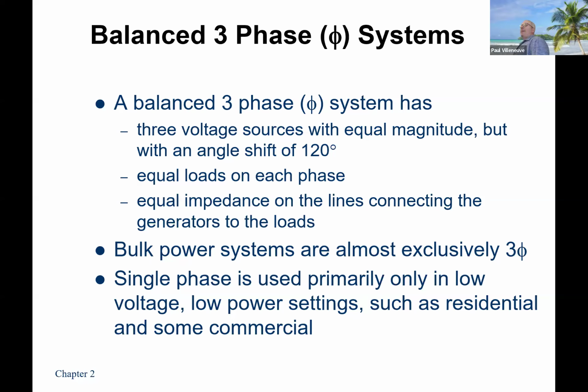We'll talk about three-phase power systems because that is what the utility world works at. This building is fed with a three-phase transformer. I should back that up. It's 3 single-phase transformers connected, I believe, a Y on the high side and a Y on the low side. Does anybody know where the transformers are that step down the power coming into Barrows, old Barrows, not new Barrows? That's new Barrows. That's a pad mounted transformer over between Neville and Barrows.